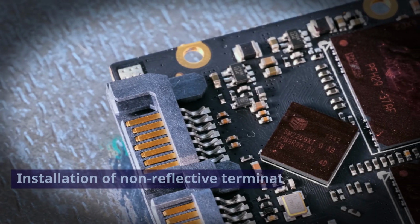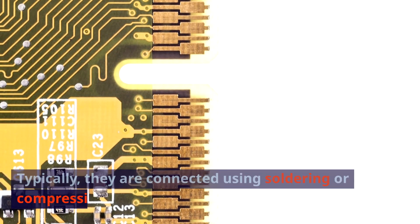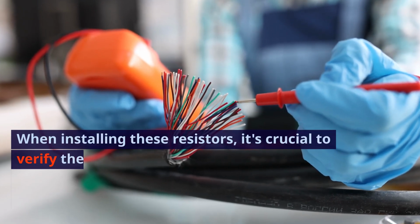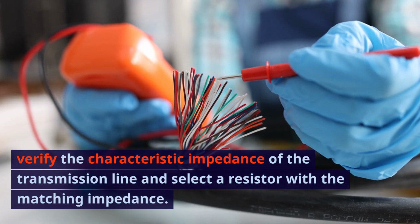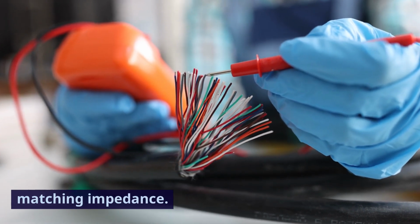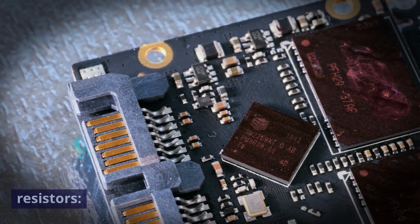Installation of non-reflective termination resistors. Non-reflective termination resistors are connected at the termination point of a transmission line. Typically, they are connected using soldering or compression methods. When installing these resistors, it's crucial to verify the characteristic impedance of the transmission line and select a resistor with the matching impedance. Maintenance of non-reflective termination resistors.